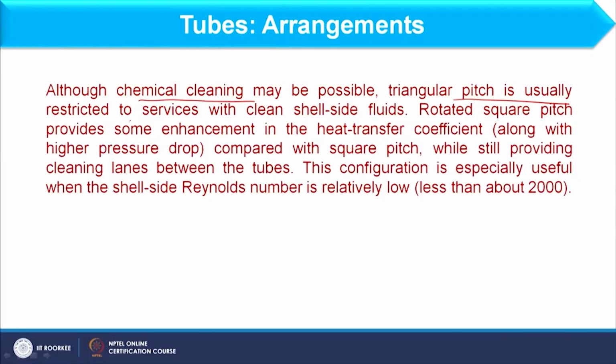If you remember the order of priority by which we allocate the fluids to shell side or tube side, if corrosion is more or fouling is more, that fluid we allocate to the tube side, and the reason is this only, because the gap is very less and cleaning is very difficult in the shell side, right. So, we should allocate clean fluid to the shell side. So, although chemical cleaning may be possible, triangular pitch is usually restricted to services with clean shell side fluid, that we have already discussed.